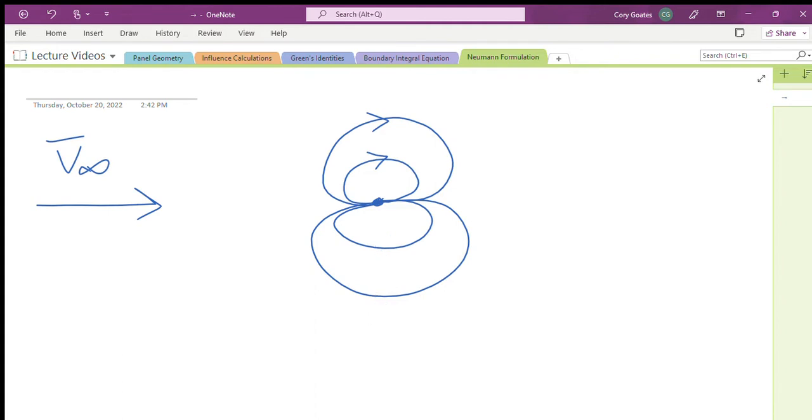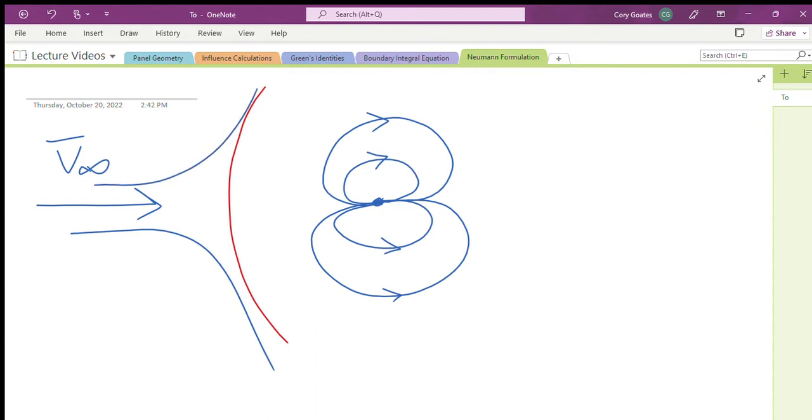You'll remember, I think this was one of the homework problems, that I asked you to consider the point where, when we superimpose these two flows, there is a stagnation point. There's a division made between this oncoming free stream flow and this doublet-induced flow here. And at some point, these two flows resulted in zero velocity at our stagnation point, right about there.